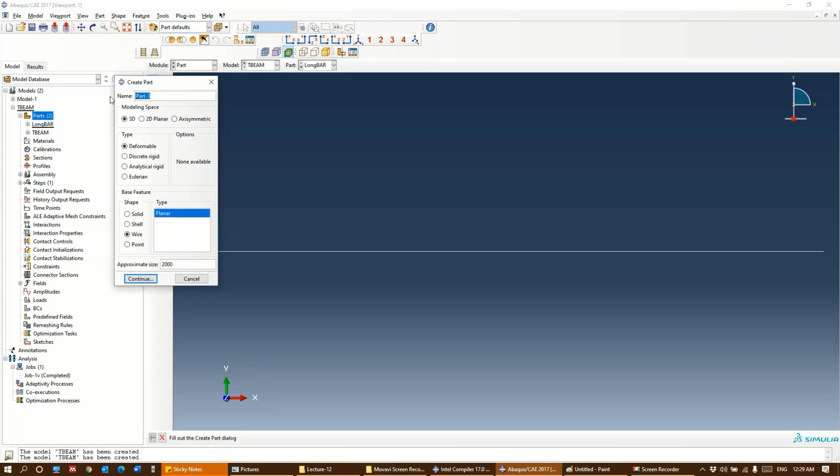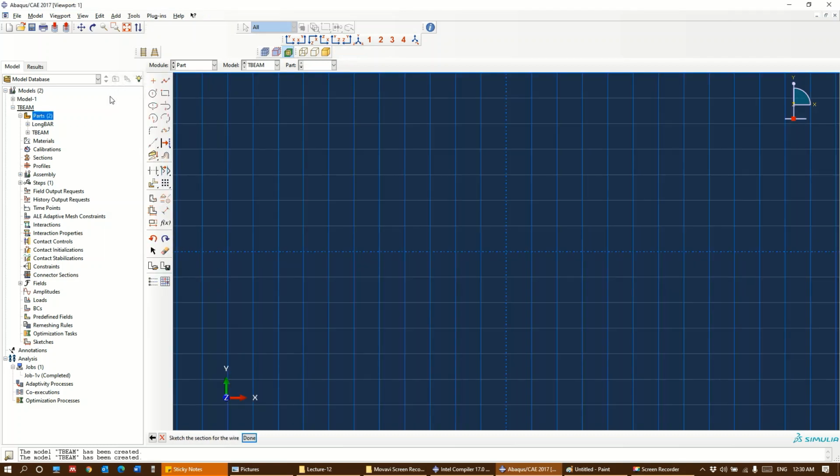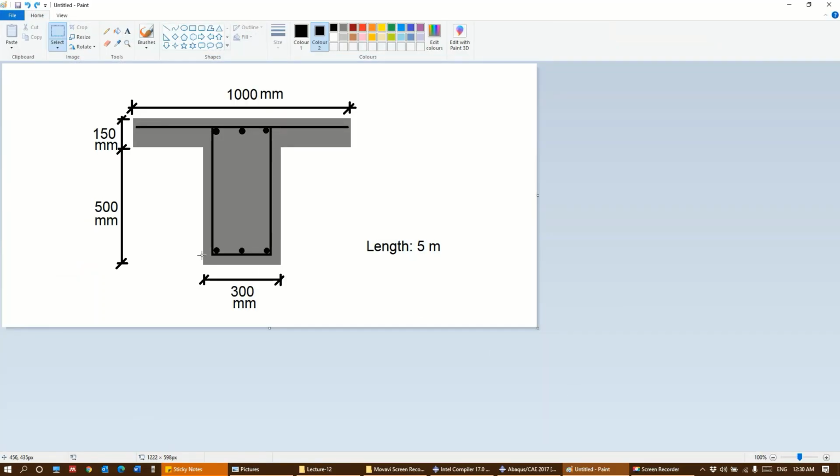And next rebar is going to be the stirrup. So let's call it stirrups. So it's going to be again wire element, and the easiest way to do that is to just draw a rectangle. And what are the dimensions of these stirrups? Let's go to this image. Assume that I'm taking 25-25 cover from either sides. So that's going to give me 250 over here, and this is 500 plus 6 plus 110, that's 650 minus 50, which gives me 600. So it's 250 by 600.